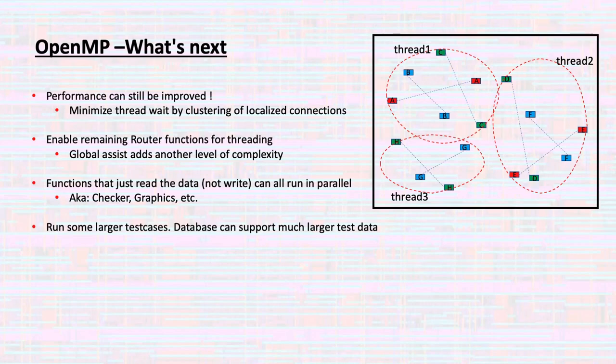In the beginning, you said you are starting with the long nets. Yes. Isn't that kind of counterproductive instead of starting with the small ones? No, absolutely not. Did you run experiments on running it vice versa? Absolutely. Even without threading, you really want to do a shape-based router long to short, because you want to put the long ones in as straight as possible. If you do it the opposite way, you're going to have all these little tiny segments all over, and then when you get to the last long connections and start putting them in, it's going to jump up and down and add thousands of vias.